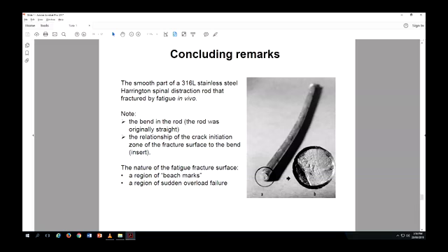So what happened here is that they have bent it, right? So there has been a lot of bending in the structure, and then the thing has been moving cyclically a lot. And why do we say that it's been cyclically moving and the failure is because of fatigue and not all of a sudden? If it was happening all of a sudden for a brittle material, you would have one separation in the entire cross-section, right? If you had it in a plastic thing, you would have a uniform separation of the cross-section and the crystals.